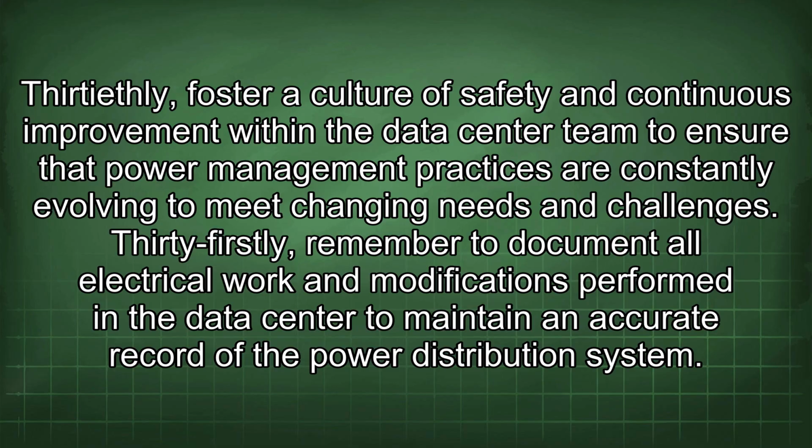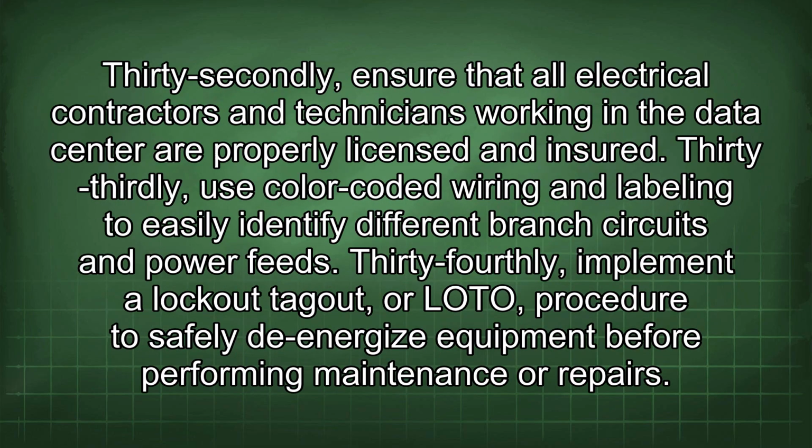31stly, remember to document all electrical work and modifications performed in the data center to maintain an accurate record of the power distribution system. 32ndly, ensure that all electrical contractors and technicians working in the data center are properly licensed and insured. 33rdly, use color-coded wiring and labeling to easily identify different branch circuits and power feeds.